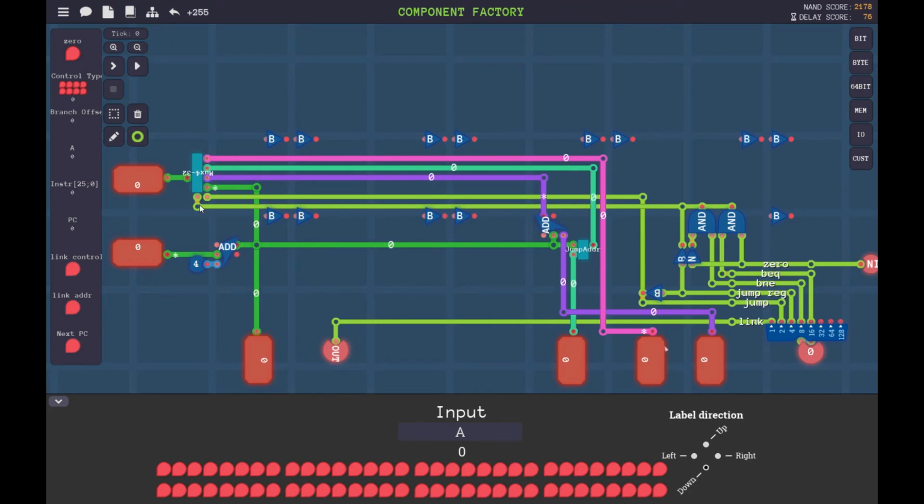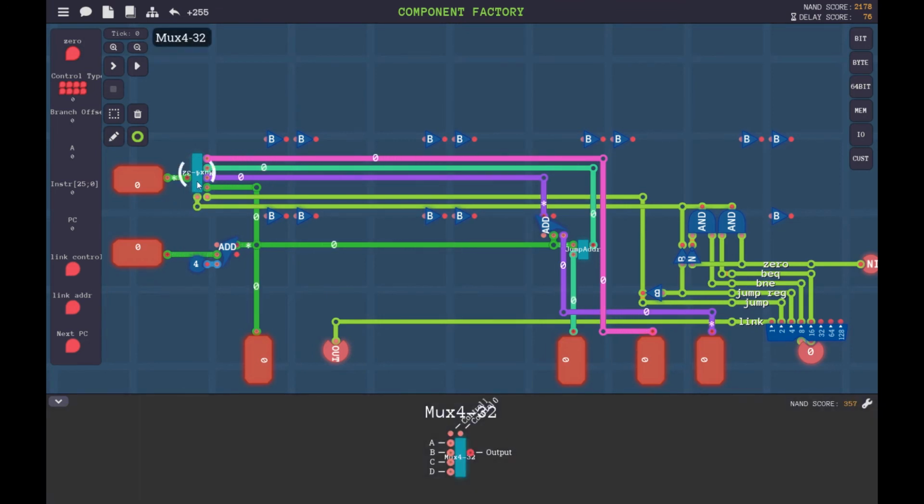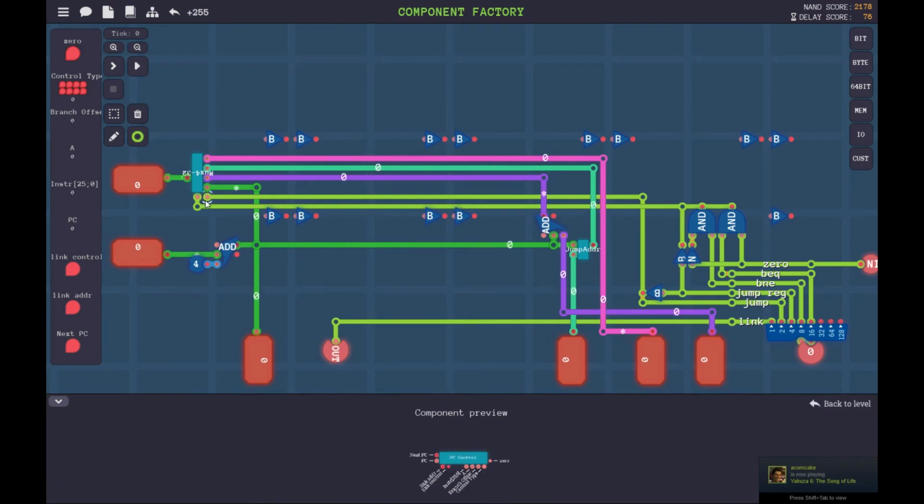So finally, the rest of the control logic is just how do we decide what control signals to send to this multiplexer. And so this is where you might notice that the inputs to this multiplexer were coming in a particular order. Both of the absolute jumps were in the upper 2 options, and the things that aren't absolute jumps were in the bottom 2 options. So that's very convenient. It means that the most significant bit of control, which is this one, should come on only when we're doing a jump instruction. So you can see over here with this buffer, we've essentially constructed an OR.